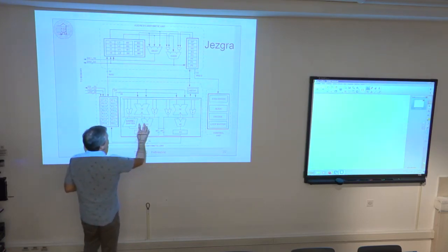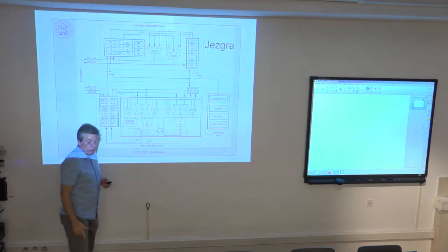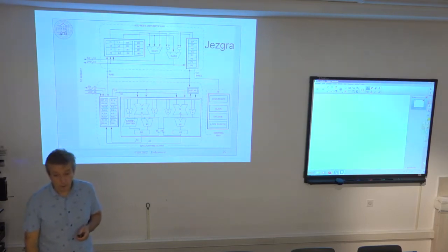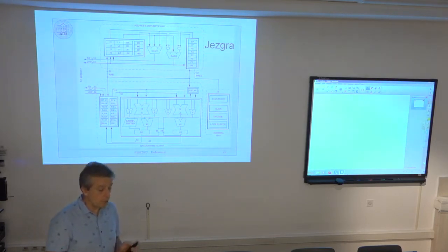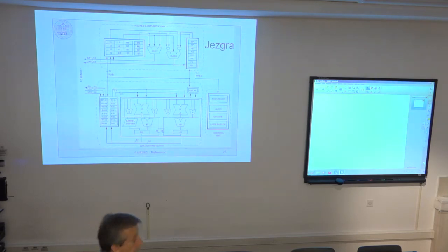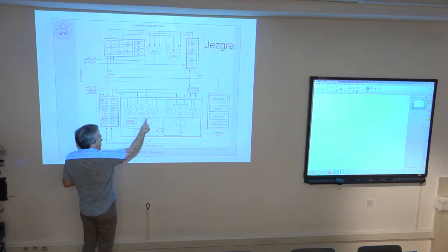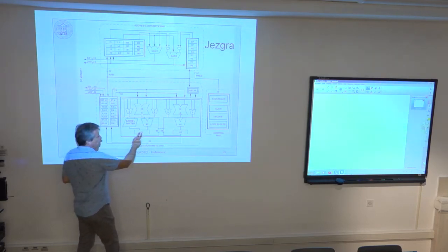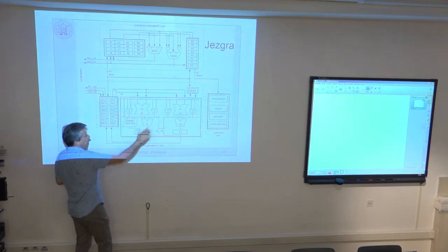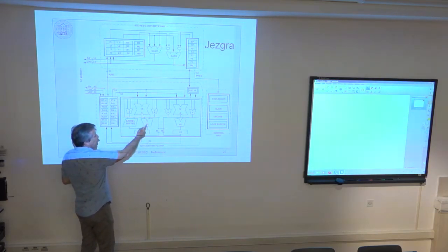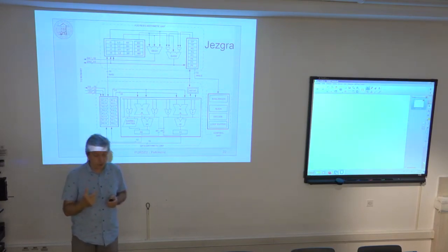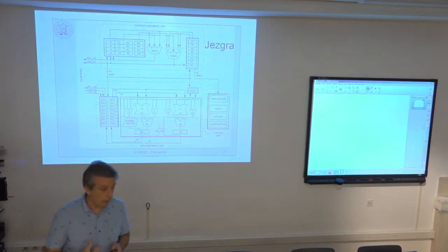They are of the same width as they were with this 21XX CPU. They support multiplication of two 16-bit input values, and they get finally one 32-bit double word product. And this product can be accumulated into 40-bit accumulators A0 and A1, since I have two multipliers. Actually, it is the same 8-bit extension as we had on the described architecture.